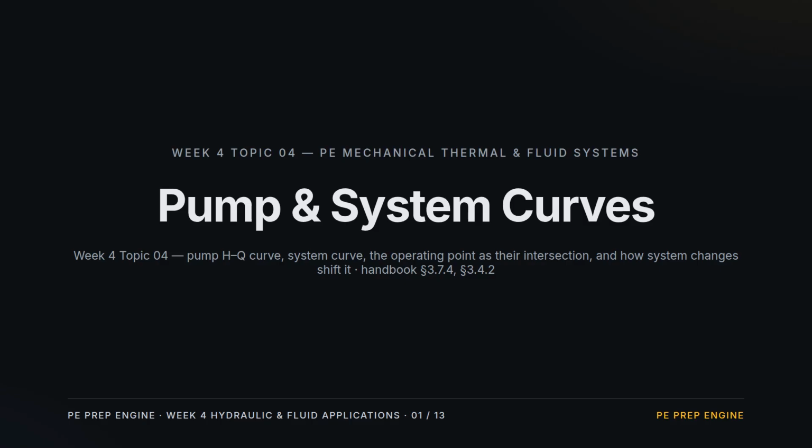Topic 4 of Week 4, Pump and System Curves. One of the highest yield ideas in the fluids section. A pump can deliver a whole family of head and flow combinations. That's its curve. A piping system demands a whole family too. That's its curve. Where they cross is the one point the pump is forced to run at, the operating point. We'll build both curves, read the intersection off an example, then watch throttling, valves, and elevations slide that point around.